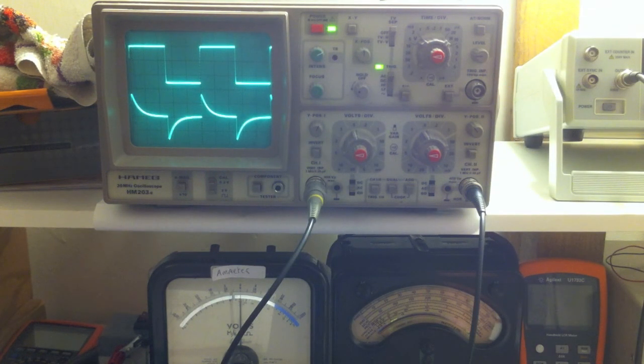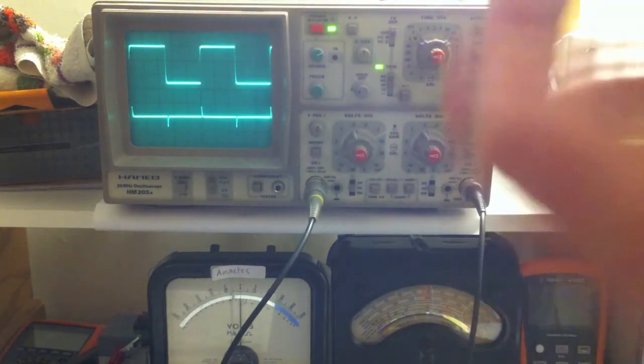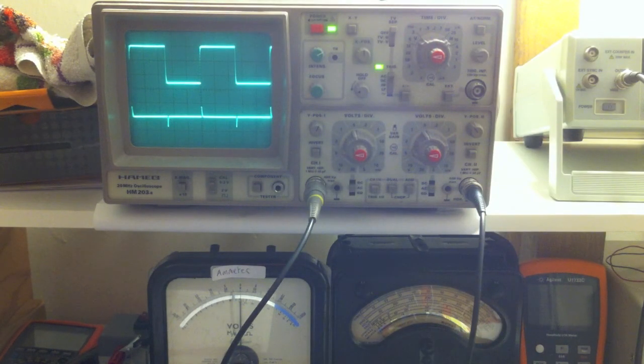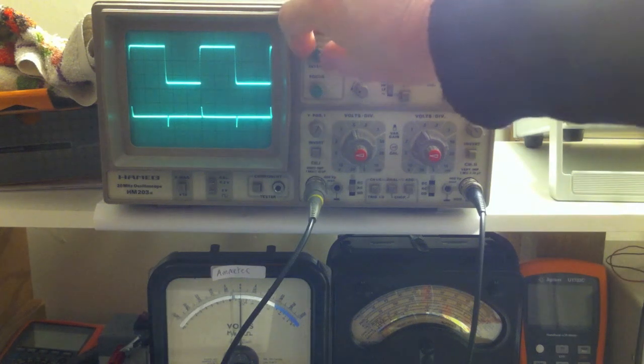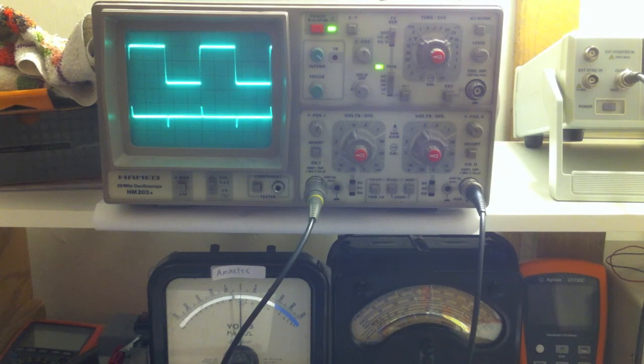If we bring the resistance right down, let's bring that right down. The lower we make this, you can see the lower we make the resistance, the faster the charge is going to go up. So this charging rate is going to be much quicker. So then we get a much closer representation of a differentiator. So that's the square wave.